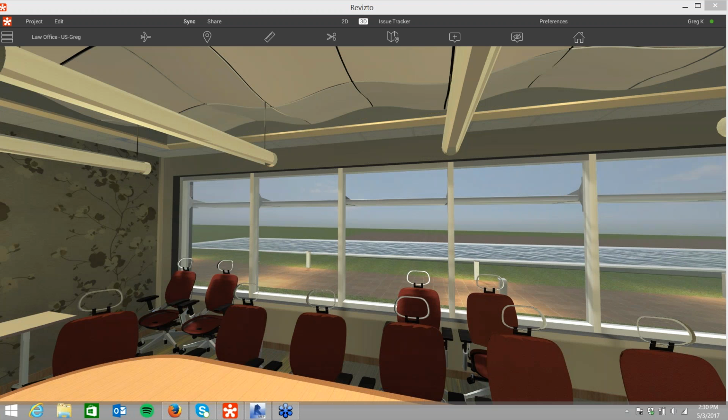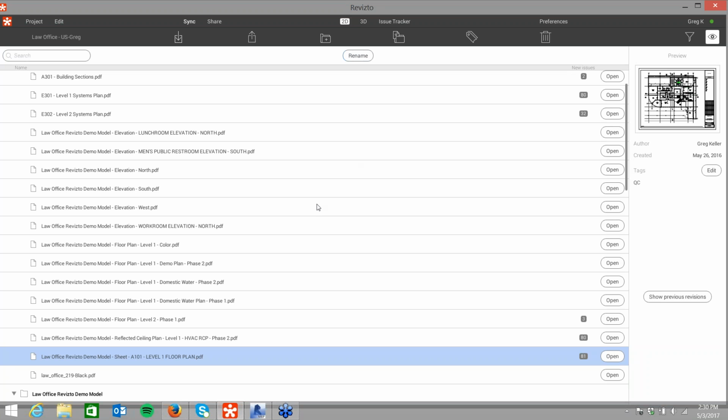So another question here. Once you set up a PDF overlay, if you upload a new version of the PDF, same file name, do you have to go through all the steps again? So James, no. Again, as I said, once you bring in that PDF, you set up that overlay one time. Even if you re-export or re-import the up-to-date version of that PDF, as long as the title does not change, then that overlay is automatically going to stay in the same exact spot.